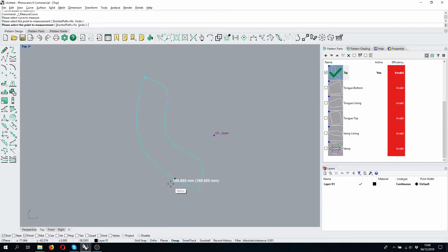And here what I can do also, that is a nice help for pattern engineers, is that whenever I am at a distance that I'm interested in, say 3 centimeters here, I can click and I can reset my distance measurement, and as you can see I am measuring now from the second point, and I get in parentheses the measure from the first point.